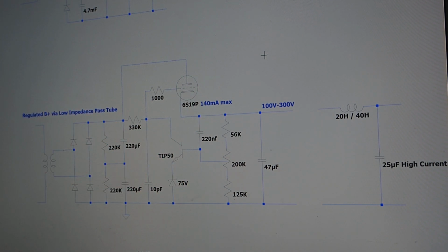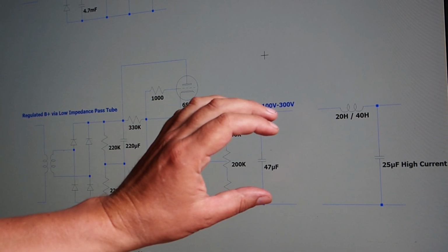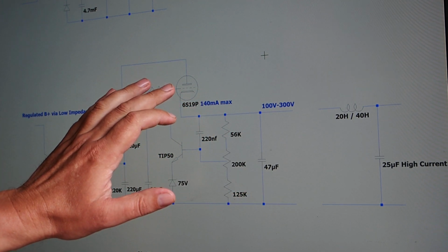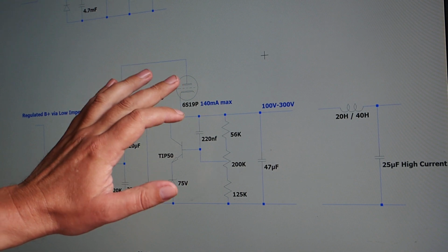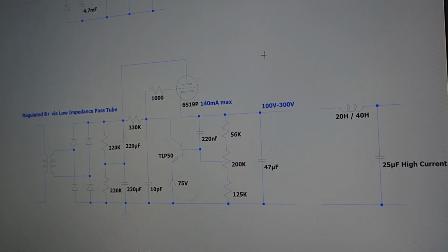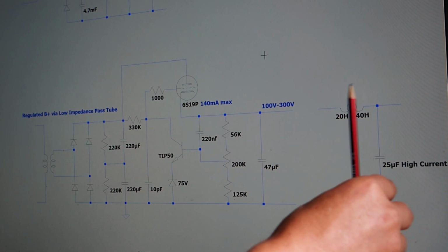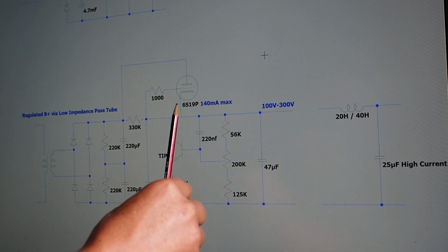However, probably not as good as some people who will really go all out on their inductors and do a two-stage LC network to flatten the signal. However, this at 200 ohm is not too bad if you have two of them. I use one at the moment, 400 ohms. And its limitation is its ability to instantly deliver current. Now, the nice thing about an LC stage at the end is that this becomes a current source by itself, so we're overcoming that partly.